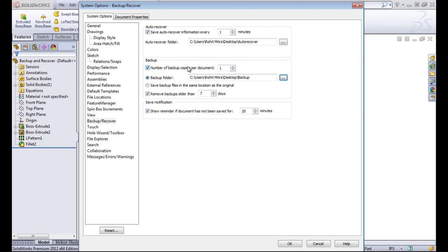And by default this is turned off, and you may want to keep this turned off if you're working with a certain number of files or more. In this case we're saving out backup copies that are going to stay saved for, in this case, 7 days. You can always change this to less or more. But if you're working with 1,000 files at a time, that can mean writing 1,000 files to the backup folder. So the backup settings make more sense for people who are working with a smaller number of files. If you're working with 5, 10, 20 files at a time, setting up a backup folder makes perfect sense. If you're working with thousands of documents, you probably want this turned off.